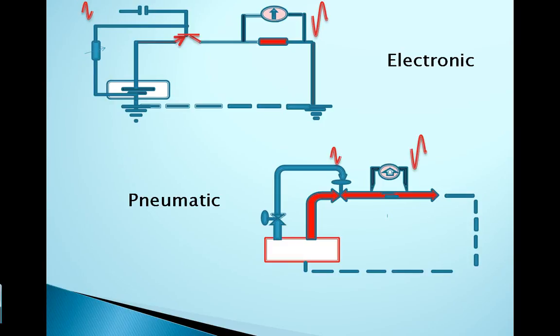By opening it to some standard level, so as to be able to pass both positive and negative, we then apply a signal, a sine wave, through a capacitor to that base, and that modulates the base up and down. In doing so, the current that goes through is also modulated up and down, and a very small current on the base causes a big current change through the device.